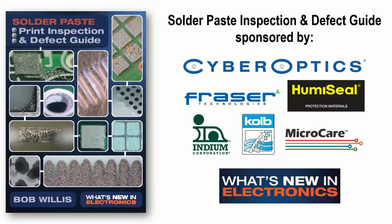So again, it's thinking about what you're printing through. Certainly you want to be just wider, or just slightly larger than the print area you're going to be printing. If you try and print with larger blades across a surface, you've got to have something to lubricate those blades, which is the solder paste. So you're moving solder paste up and down on your stencil for no value. It's costing you money to run, so that's not a good practice. So you're trying to get that size of blade appropriate to the print area on your stencil.